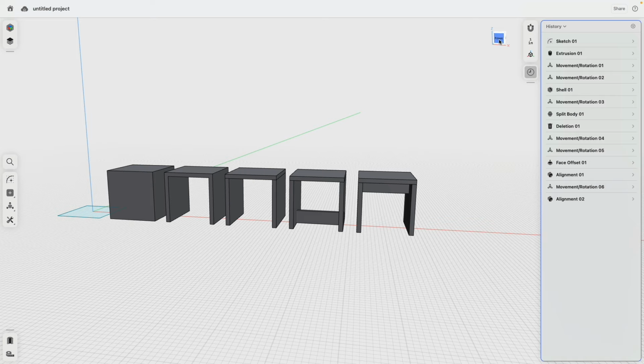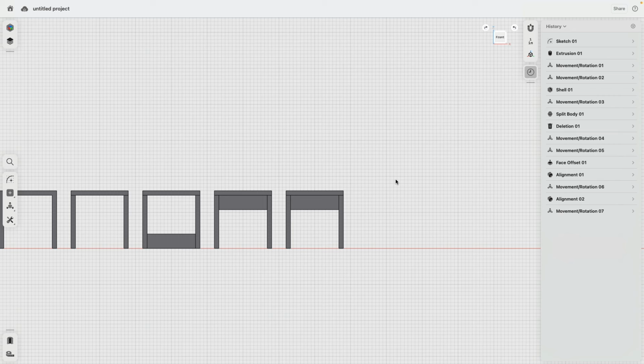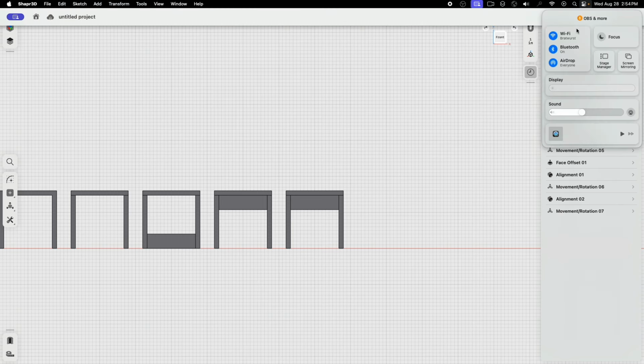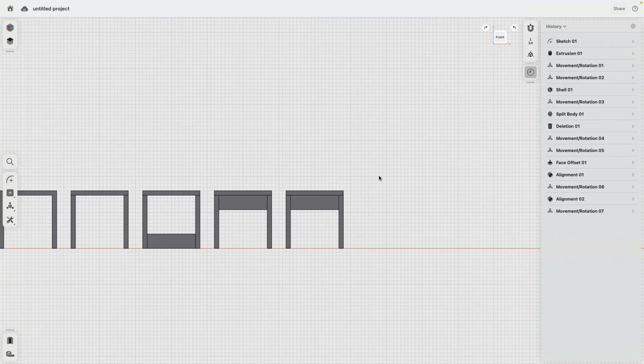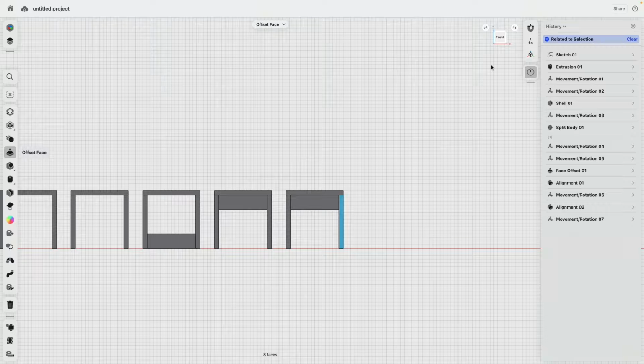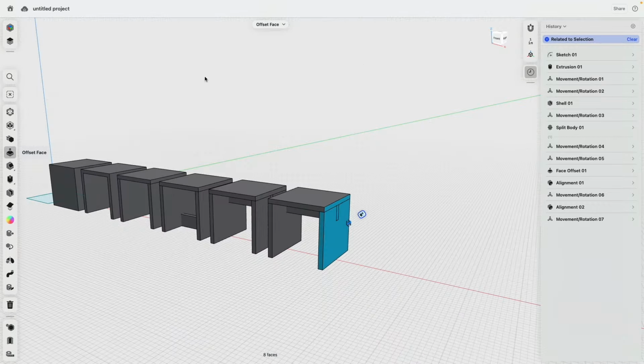Now, let's go to the front view. Select all this. Copy and go over. Very good. And what I will do now is I will click from the left to the right, press tab till I only have faces. So you see now I have all the faces here selected.